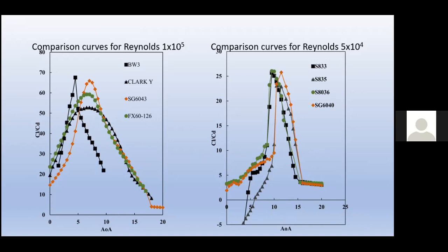It was found that the airfoil with the highest curve was the BW3, followed by the SG6043, which was selected at the end because its curve didn't have such abrupt changes between each degree of the angle of attack, and may be advantageous for possible changes in wind speed suffered by the turbine.